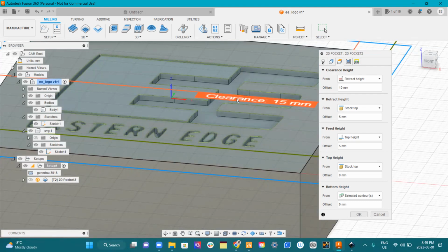The reason that's there is because my clamps stick up a bunch. They are really high, like 23 millimeters, right? And so this is saying, well, 10, is that clear enough? Because I know that once I get down here, I'm not going to go outside of the wood. I'm not going to hit the clamps. This is why these limit switches and emergency switches are important, because I'm making a decision now that I'm not going to go high enough to get over these clamps. But if something goes wrong and it starts doing something weird, it might just plow right into the clamp and then break the clamp and the drill bit and the whole machine.